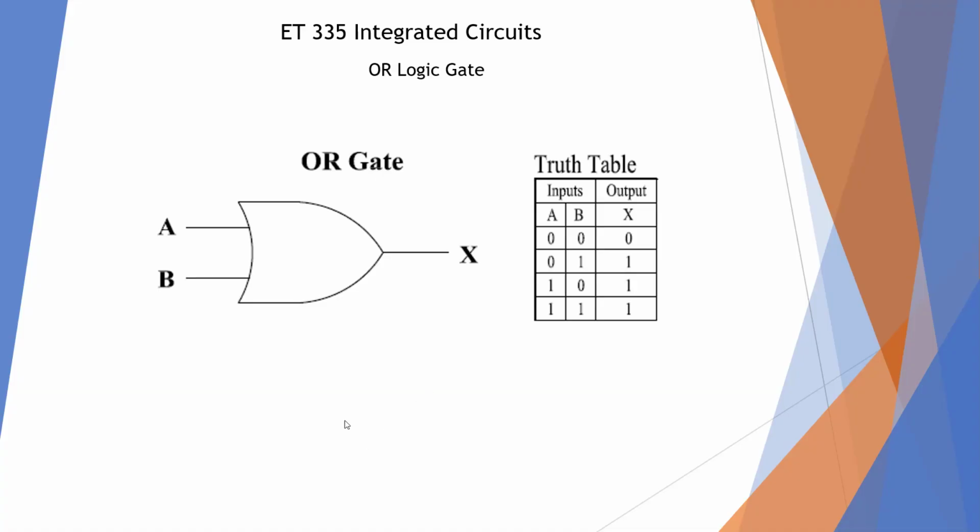Here's our OR gate. Again, our unique condition 0, 0 is 0. So we're going to mark everywhere on our waveform where there's a 0, and where they combine, we're going to put a 0 down. We could go the other way, but it'll be a lot more work and more confusing.